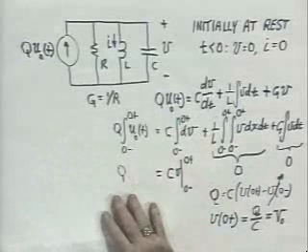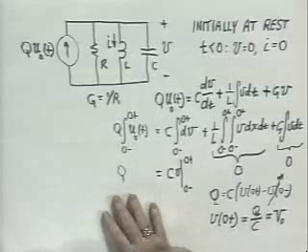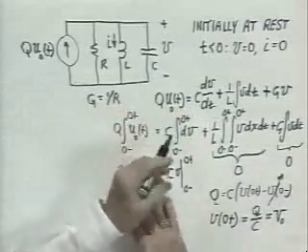We want to solve this differential equation to evaluate how V responds with respect to time. Now notice that once the impulse has passed, the left-hand side of the equation is 0. That is, the impulse has value only for t equals 0. So the left-hand side disappears, and we're left with the differential equation for the circuit, which has no driving function. That is, we're left with the homogeneous equation. In other words, the circuit, once the impulse has passed and charged up the capacitor, is unforced. So what we're going to see here is the natural behavior of an RLC circuit.